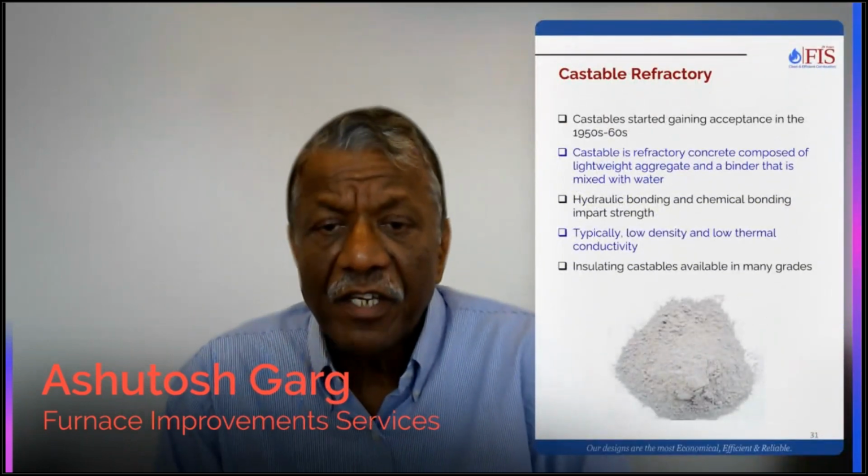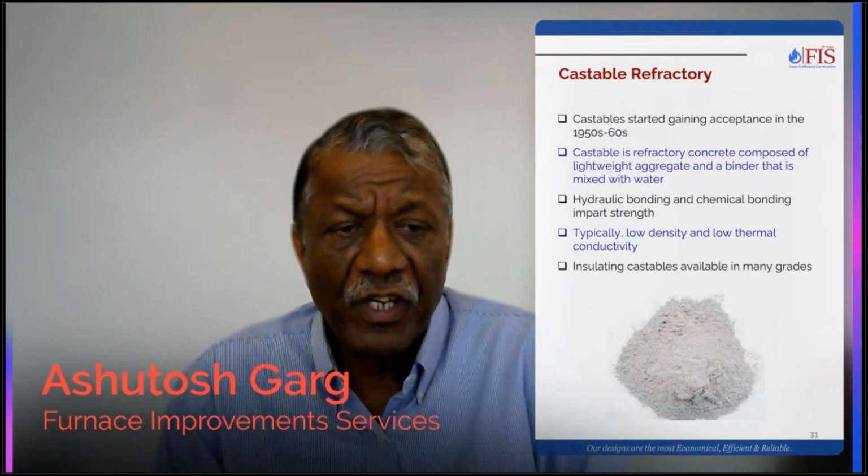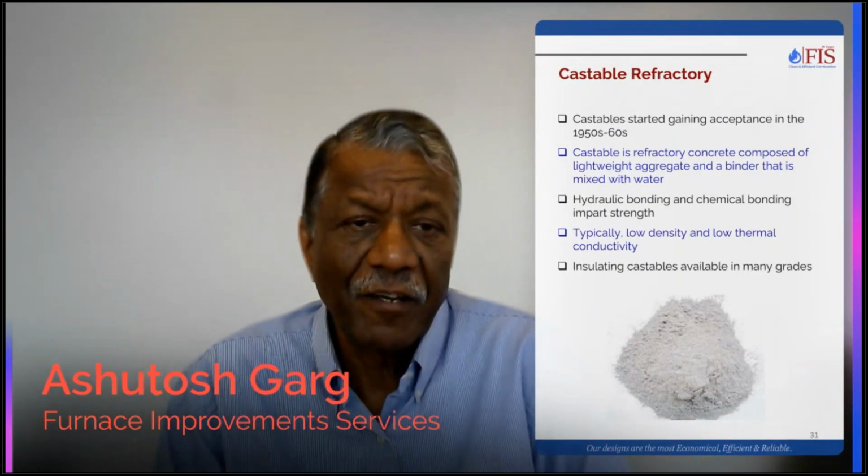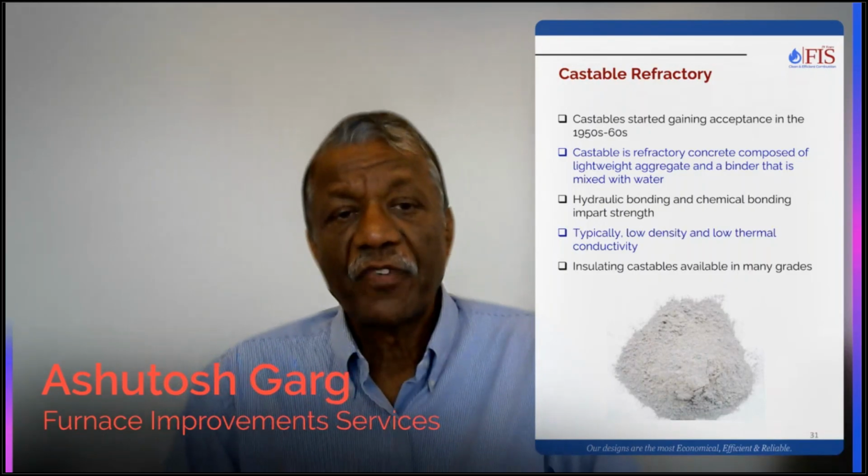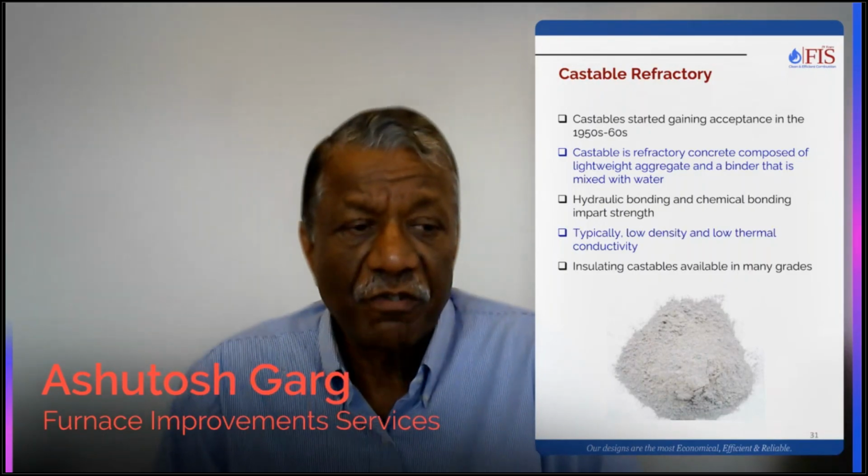Generally, ceramic fiber modules are used wherever you need more than 4 inches of lining. Anything more than 4 inches, we can use ceramic fiber modules.